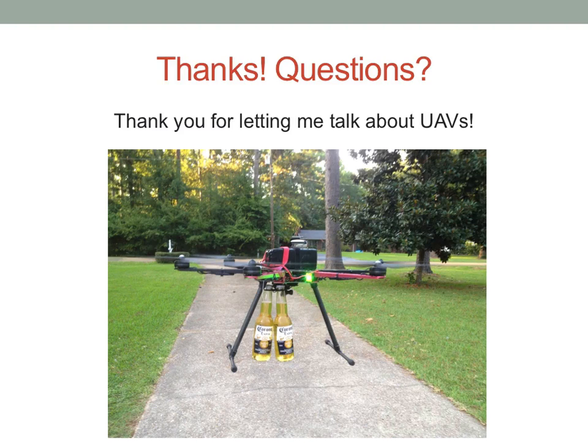Right. These do not. There's one that we just put on order called the DJI Inspire 1 that on the bottom of it has 2 sonic sensors and then 1 image stabilization sensor. Now, what it uses that for is not terrain following, but while it's indoors. So these use GPS while they're outside to maintain a stable position. But inside, I couldn't just let that one hover. I had to actively control it because it doesn't know that it has moved left or right, and I have to tell it. Whereas when it's outside, it follows a GPS position. It will just stay at that spot if I do nothing.